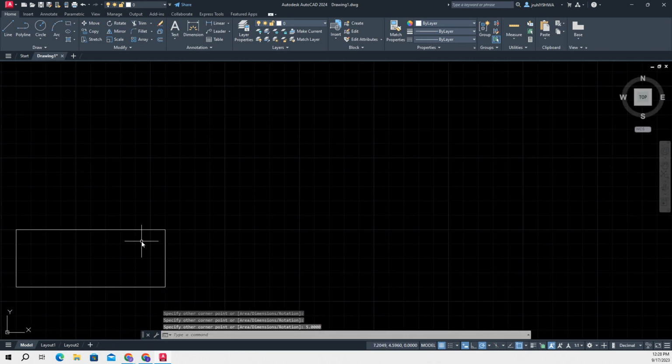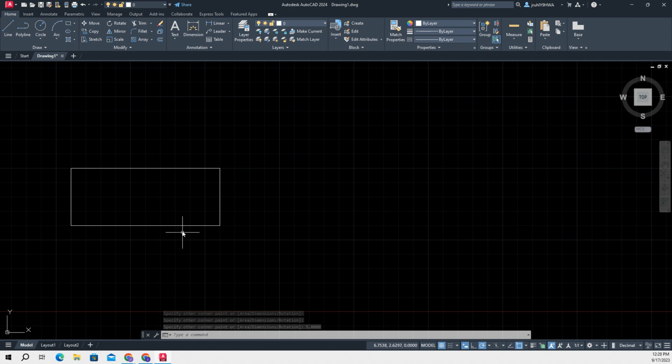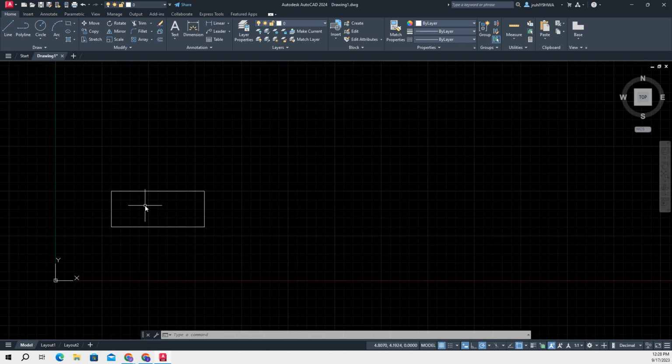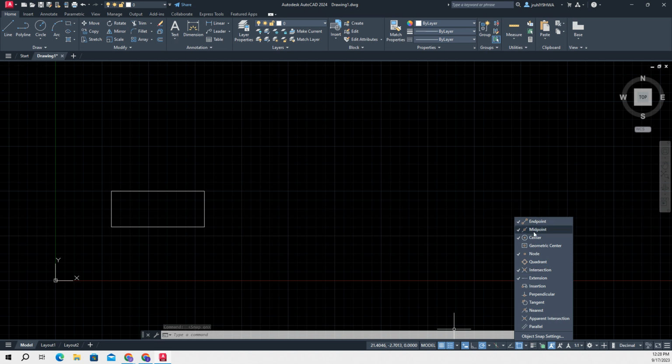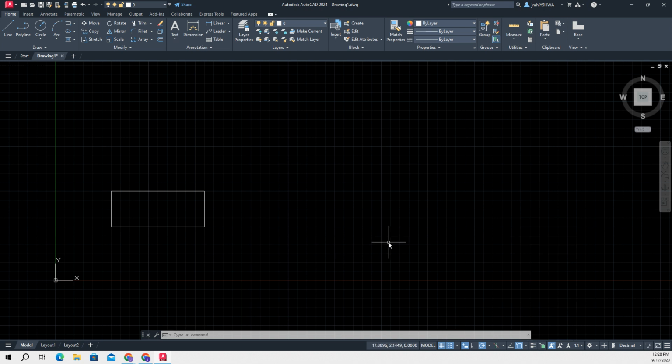All right, I'm using my flywheel, scrolling in, grab where I want to design. On the bottom, I got to make sure that my snap is on, and then I could also look to make sure midpoints is ticked on. For this one, maybe turn on geometric center. Talk about that in a second. If you notice, nothing happens yet. It's not looking for centers. It's not looking for midpoints. That stuff will start to happen once I have something selected on.